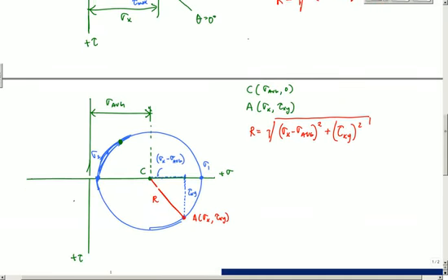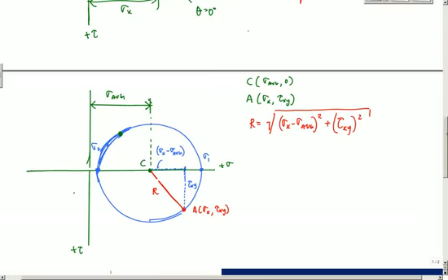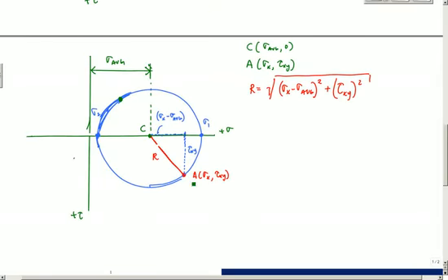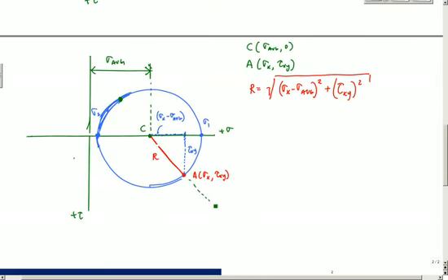One thing that's really important to understand about Mohr's circle is that this here represents theta equals 0 degrees. This represents our state of stress at x, I'm sorry, not x prime, but at x here in that original coordinate system that we drew. And here was this sigma x, and here was this tau xy, if you will. So in a way, we're talking about this face of the stress element.